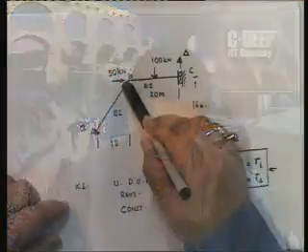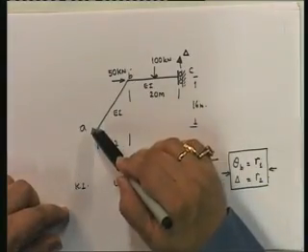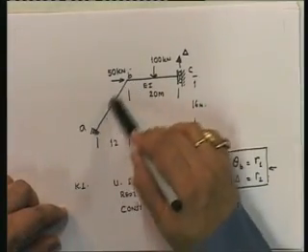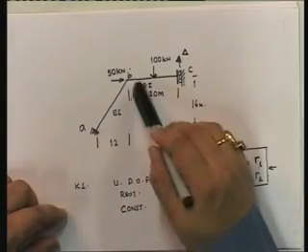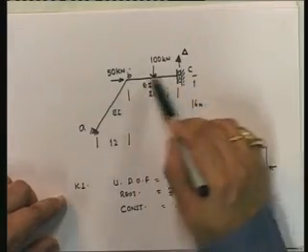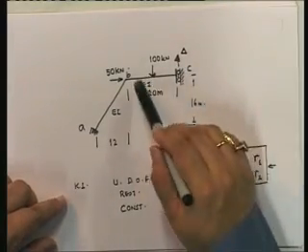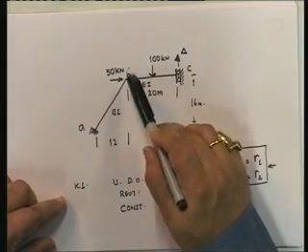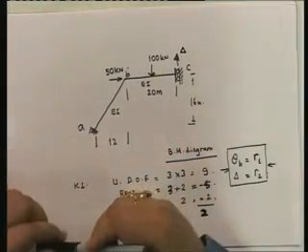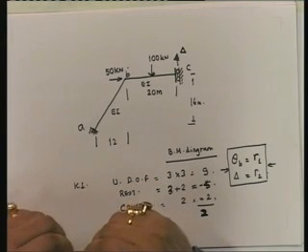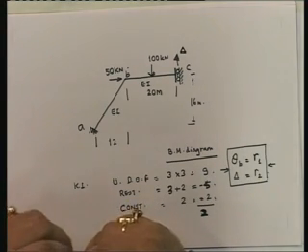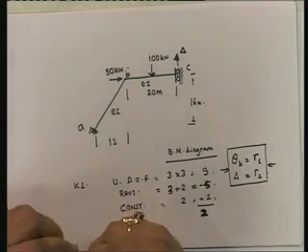We already know that. So those are the member end moments. Obtain expressions for fixed end moments. Does AB have any load on it? No. So fixed end moments at A and B, AB and BA are 0. Does member BC have a force on it? Of course. So we have to determine fixed end moment at B and fixed end moment at C. Okay. So we will do all of this in my next lecture.